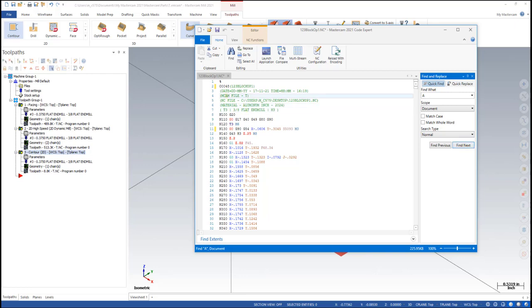All of these parentheses things are just comments. Anything within the parentheses is just ignored by the post processor or by the controller. It's just meant for the operator to be able to read. So there's no more A's, so this would work on a HAAS now.